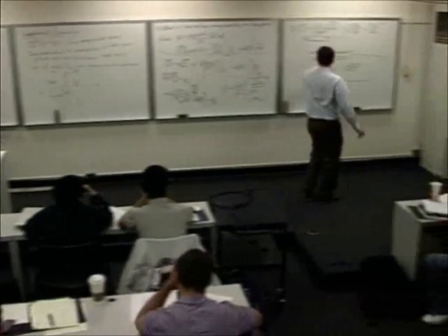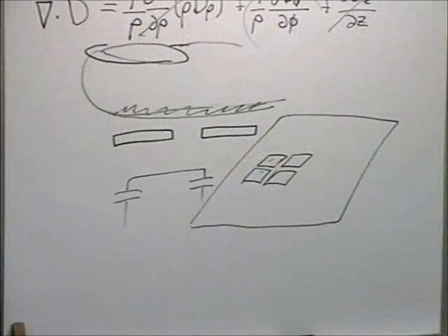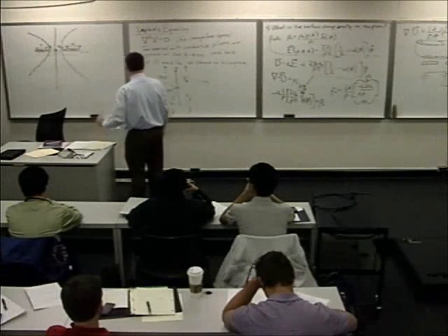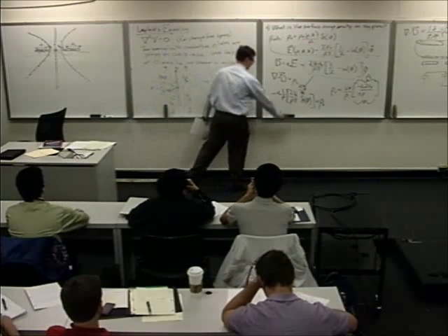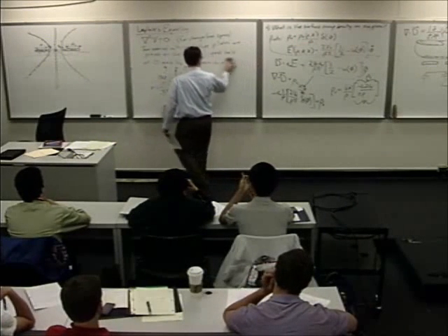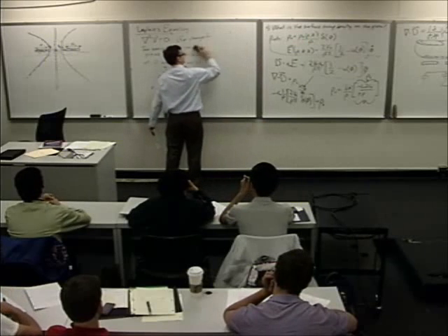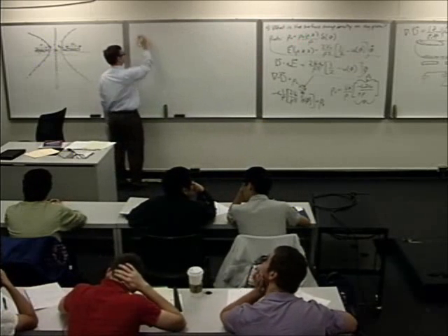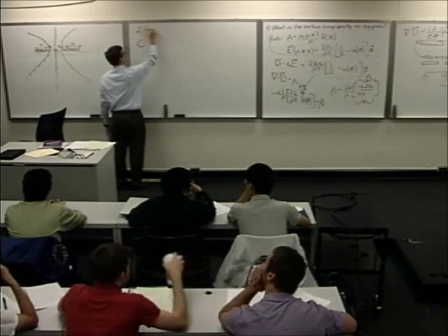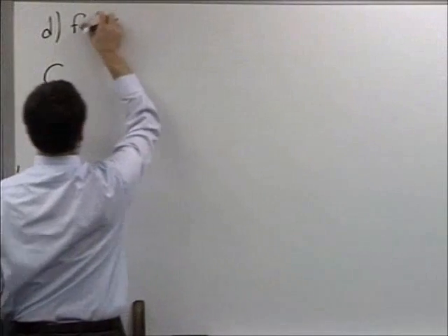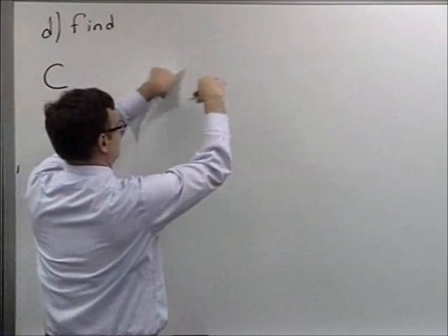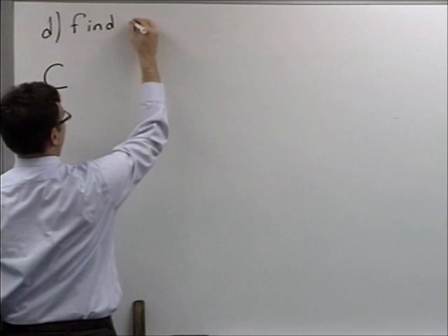So anyway, that's another use. So let's go ahead and finish up the problem, just so that you can go home and brag to your parents that you now know how to calculate capacitance for touch screens on iPhones. So remember, capacitance, this is find the capacitance of that scenario over there, where I've got two traces parallel with a little bit of gap separating.